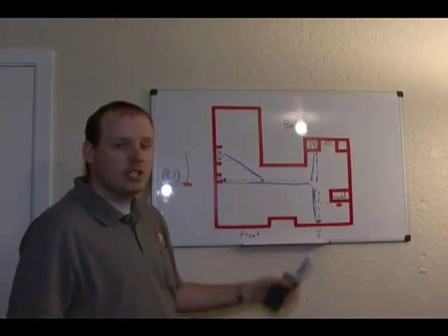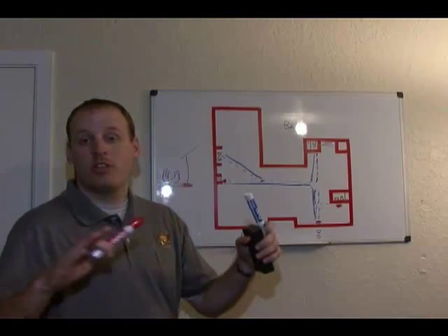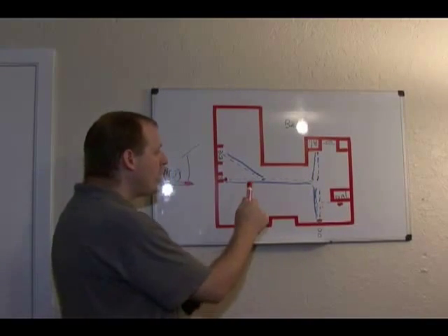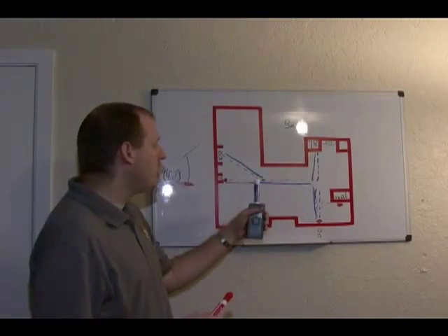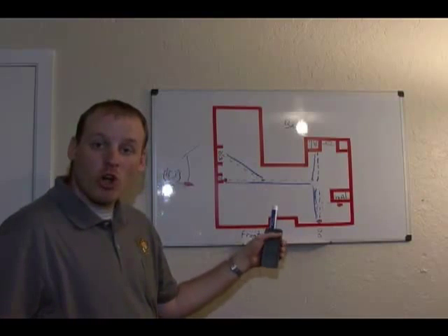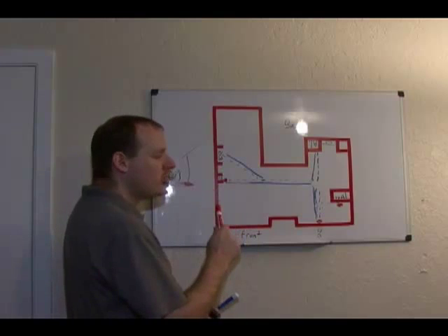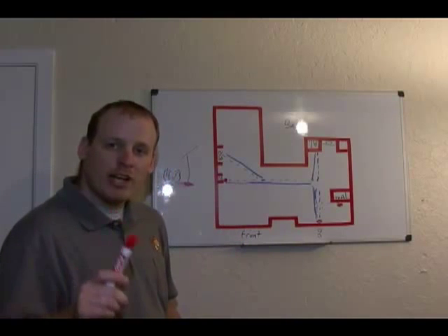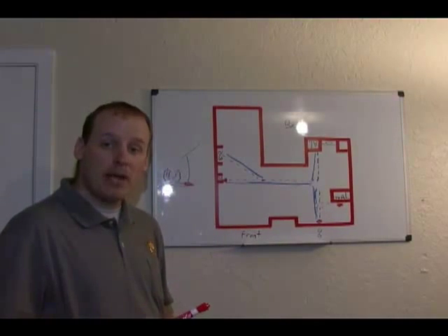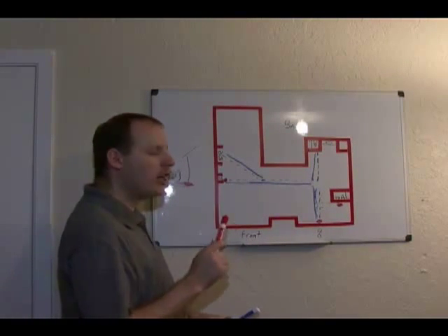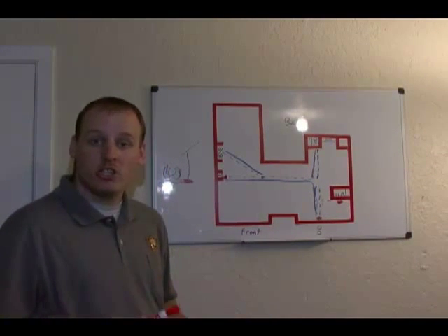There could be a situation where the dirt could be oversaturated around the actual pipes itself, so maybe there is a leak in here, but it's very, very slow, but it doesn't show a leak because it's not allowing any more water to get out. You know, all kinds of things like that. So we always say that until we do the final repair and then we test the system after that repair, we never want to guarantee 100% to somebody that there couldn't be or wouldn't be an additional leak.